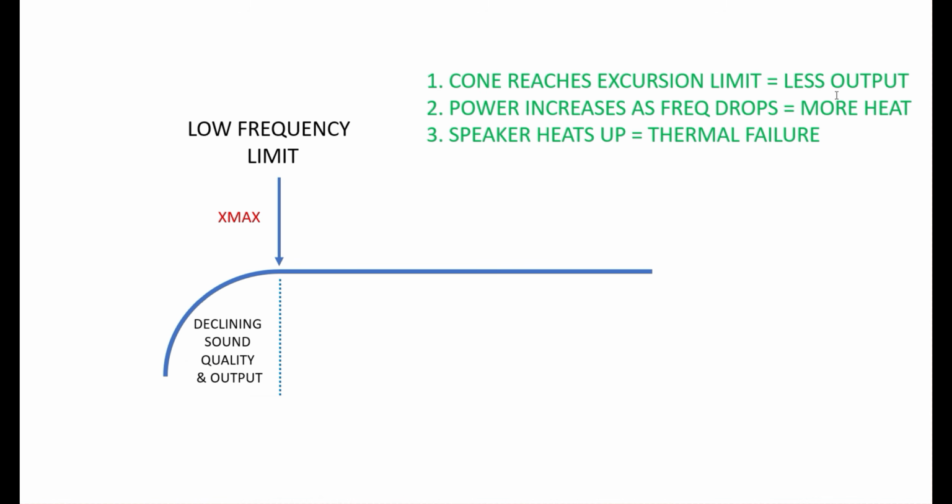And so you hit that limit, and if you try to keep pushing, you just get less and less output, right? And to move all of that air, you need more power. More power means more heat. So the more you try to push it, the more heat you generate, and eventually you end up with thermal failure, right? The adhesives in the speaker start to melt, or the voice coil burns out and fuses, or whatever.